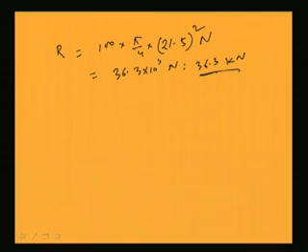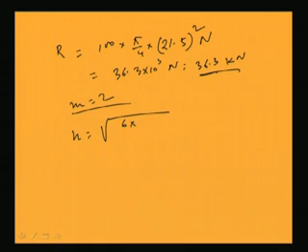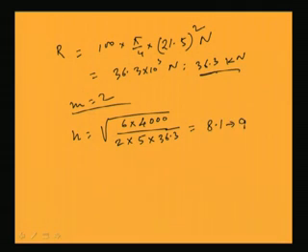Now, here m will become 2 because 2 lines of rivets have been provided. So, all the values now we have, so I can find out the value of n. n equals 6M, M means this is 4000 kilonewton centimeter, by m p R, m is 2, p is considered as 5 centimeter and R is 36.3 kilonewton. So, from this I can find out n as 8.9. That means we have to provide at least 9 rivets per line. Okay. So, we will consider that 9 rivets we are going to use.